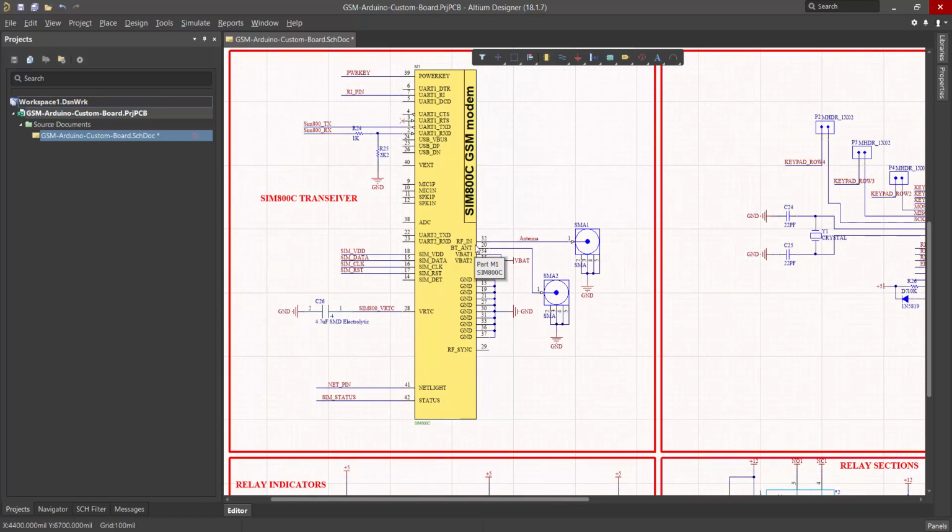The next pins are RF, here, for connecting to the GSM antenna, and BT/ANT for connecting to the Bluetooth antenna. These two pins are very important because they are high frequency signals, and also they are very sensitive. So in PCB layout, you should carefully route their tracks, okay?